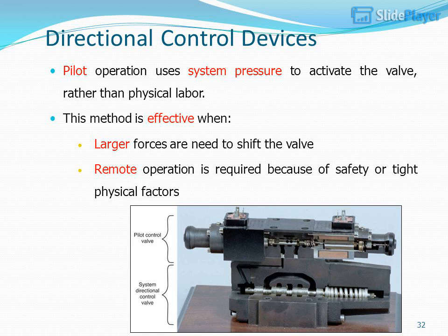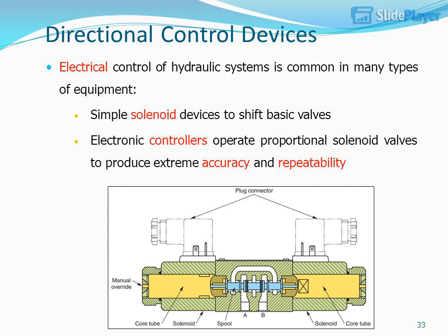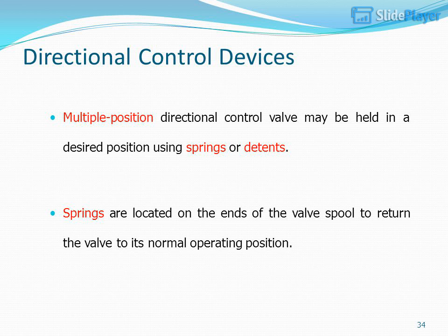Pilot operation uses system pressure to activate the valve, rather than physical labor. This method is effective when larger forces are needed to shift the valve. Remote operation is required because of safety or tight physical factors. Electrical control of hydraulic systems is common in many types of equipment. Simple solenoid devices shift basic valves. Electronic controllers operate proportional solenoid valves to produce extreme accuracy and repeatability.